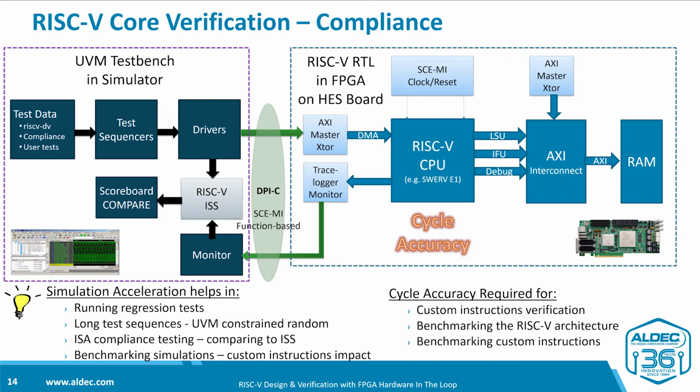Part of the test bench infrastructure are system bus transactors and monitors. In our example, a standard AXI master transactor and a custom-made trace monitor are based on the SCE-MI function-based interface and integrate very well with SystemVerilog UVM through DPI-C.